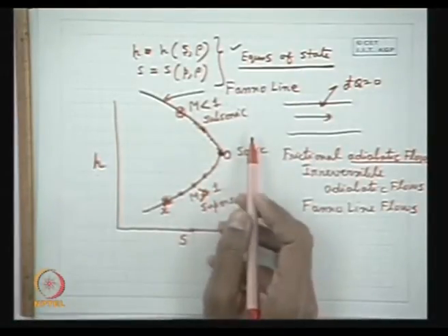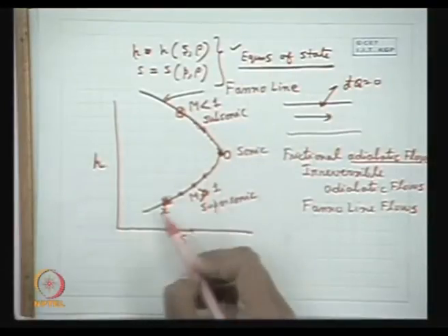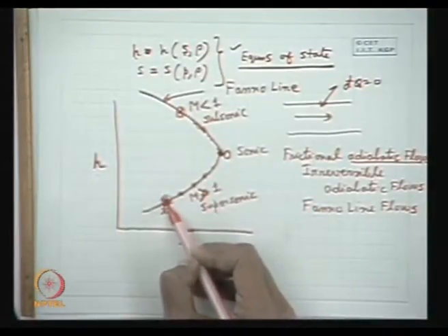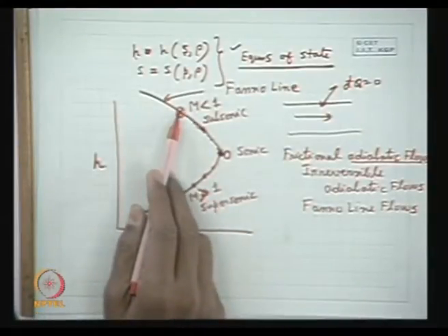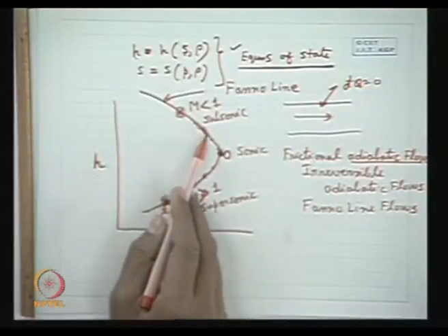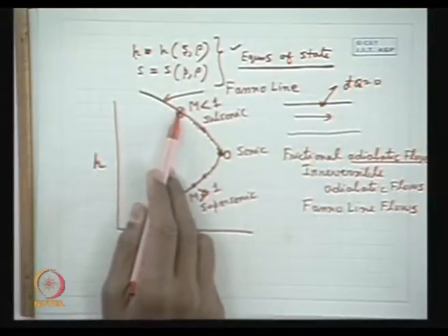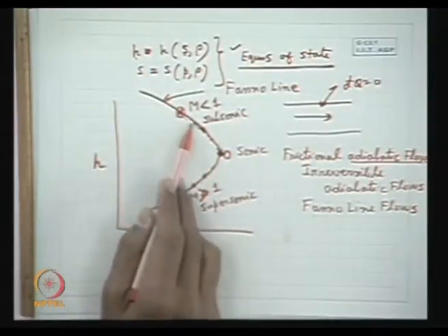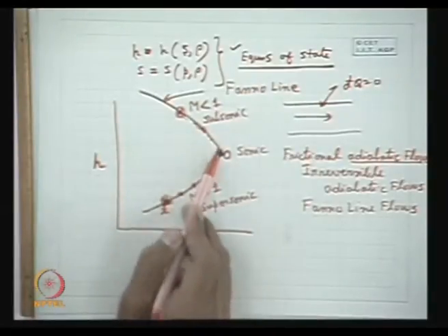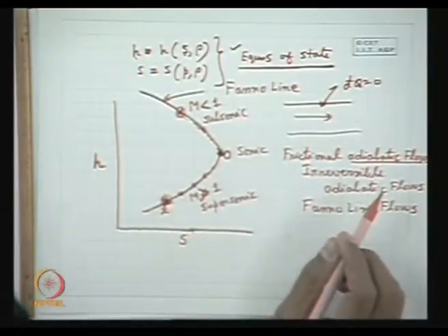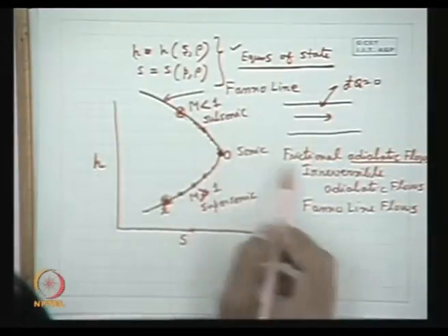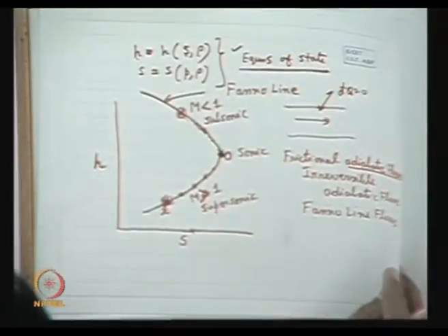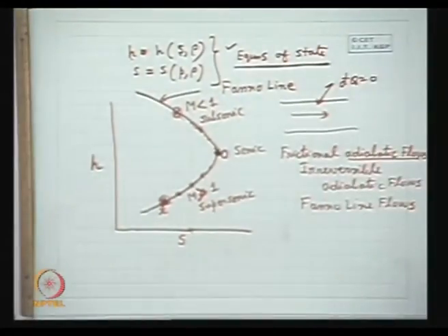A further increase in length will not change the flow unless this inlet condition is changed. Similarly, the influence of increasing duct length or friction in a subsonic flow without heat transfer will change the subsonic flow towards the sonic flow. The point moves towards the sonic flow. We will have to proceed along the curve to the right, following the second law of thermodynamics, that is, the increase in entropy for the system without heat transfer will be greater than 0.